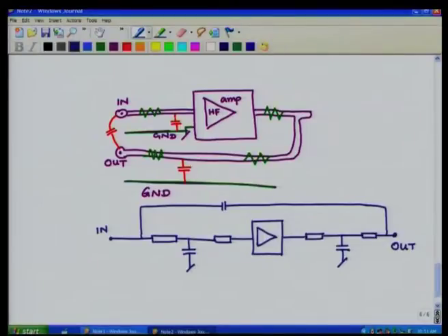So, effectively, this high frequency amplifier has a low pass filter at the front end, a low pass filter at the output end, and then you have a Miller effect capacitance coming into the picture, all because of these parasitics, which, as you see, are quite dangerous.